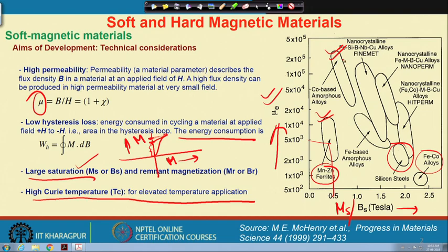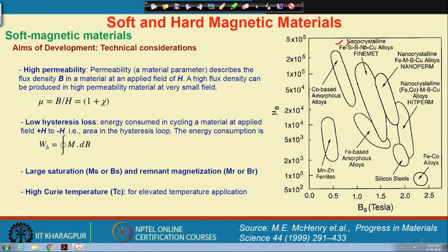The derivative of this amorphous magnet was the metglass, and the derivative of that is Finemet, which has iron, silicon, boron, niobium and copper in the alloy, so that the composition can be vitrified. We also need to consider that the glass forming ability should be higher so that it can be vitrified, which we discussed elaborately in the first weeks of the lectures.